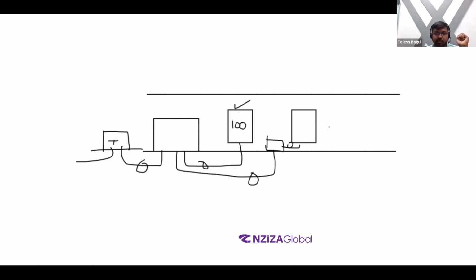So in case, let's say this is our 100 ampere panel board. This particular will be rated for 100 amperes. This is the wire coming out from the switchboard over here, which will be rated for 100 amperes. We will have 3 quantity of 3 American wire gauge for our phases. We'll have 1 number of 3 American wire gauge for our neutral.